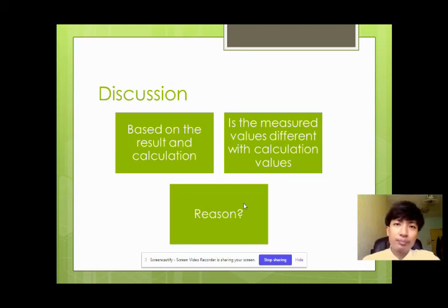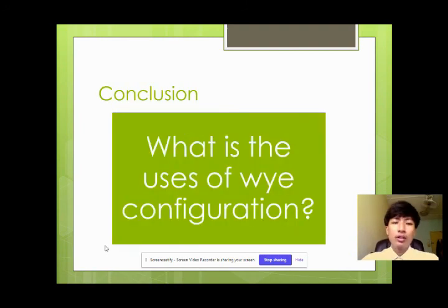So what is the use of Y configuration? Basically the Y configuration is used to distribute power to everyday single phase appliances in our home, such as office, and maybe for the school also. Since the insulation is decided by phase voltage, and for Y connection the phase voltage is 0.577 times the line voltage. For the delta interconnection, phase voltage and line voltage are equal.